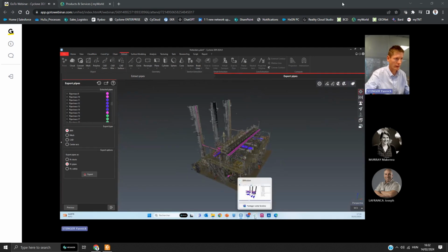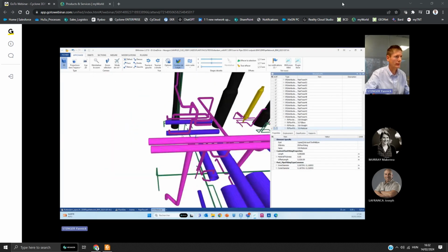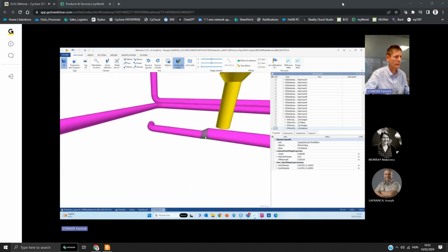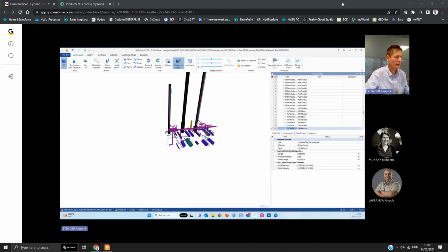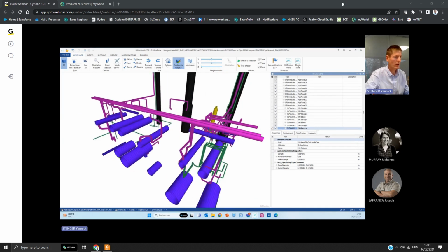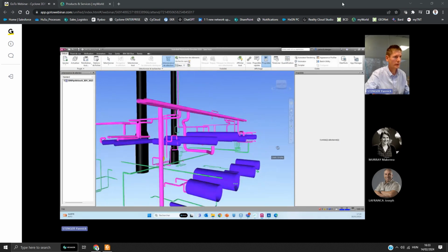So I'm going to show you what I did. So in a BIM viewer, this is the exact same project that I imported in BIM Vision just for visualization. And if I focus on what I demonstrated, my reducer, information like thickness and diameters are saved in this IFC. So I mean, IFC would be the most intelligent format for exchanging. So this is the one that we recommend, but center axis, CAD models work as well. And I also want to display in Navisworks the same model.